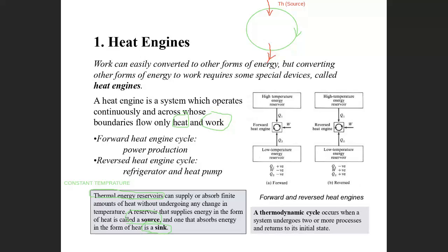For the forward heat engine, as we just mentioned, we want to convert thermal energy, or heat, into work. When thermal energy flows from a high energy value to a lower energy value, some of the thermal energy can be converted to work, because the working fluid can experience an expansion process.